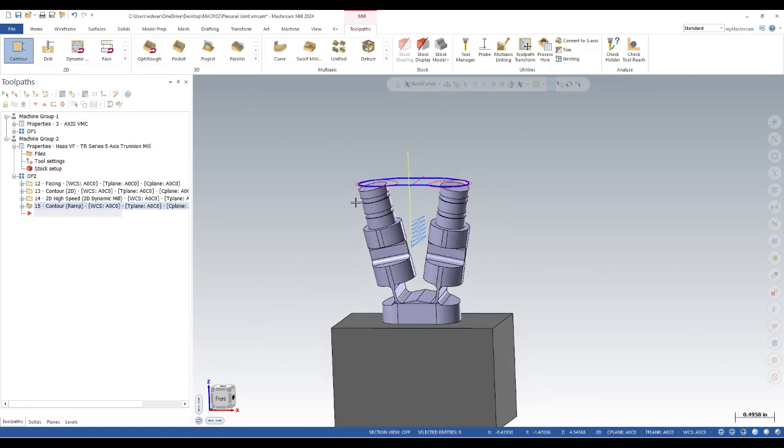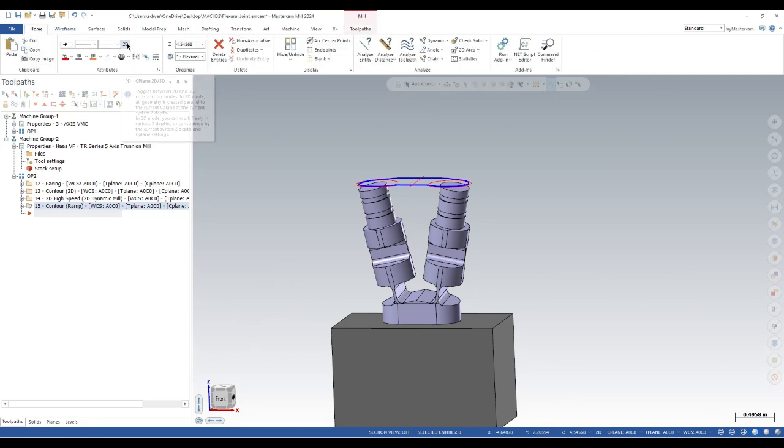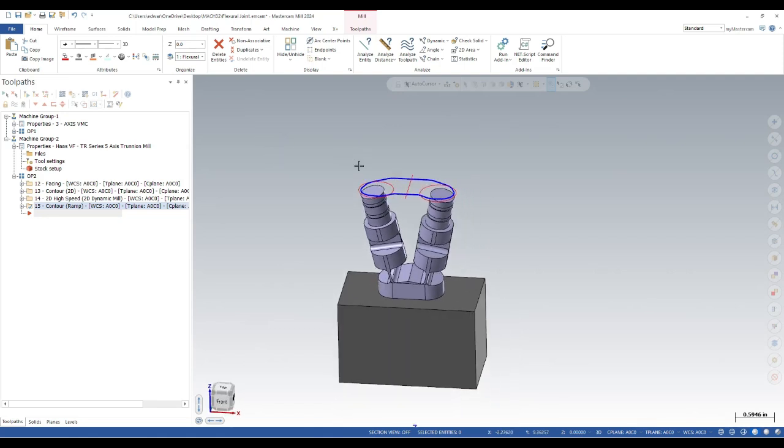And let's see, next thing, I'm going to go back to the Home tab. I'm going to switch it back to 3D mode. Put my Z back to 0. I've noticed that sometimes, because there are certain things that being in 2D mode will screw you up, making new planes and geometry and stuff like that.